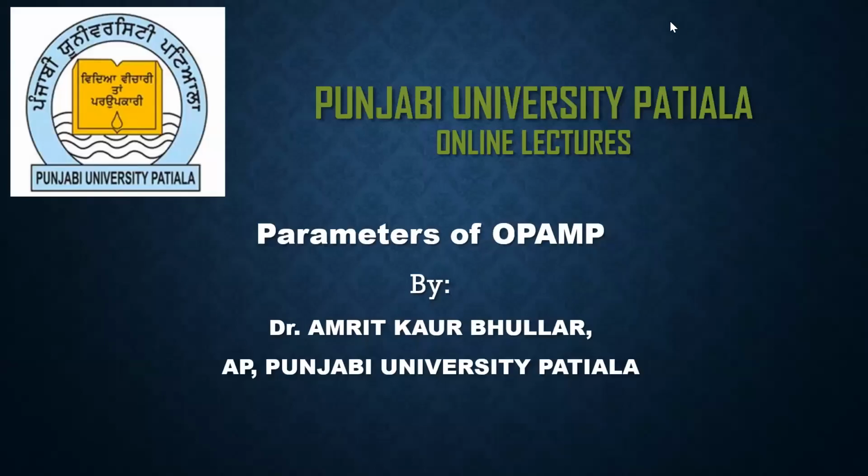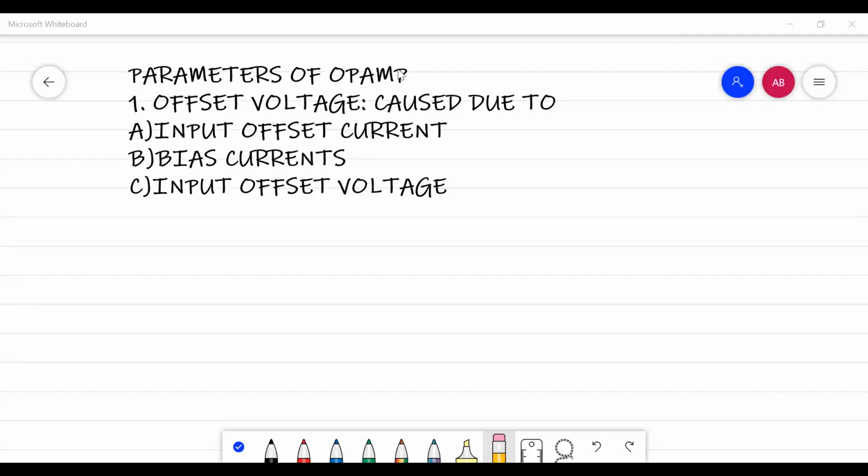Hello students, so today we are going to learn the various parameters of an op-amp. So the very first parameter that is there to define the op-amp is the offset voltage. Basically, we require an op-amp that has got a minimum of offset voltage. So this is caused due to the input offset current, bias currents, and input offset voltages.